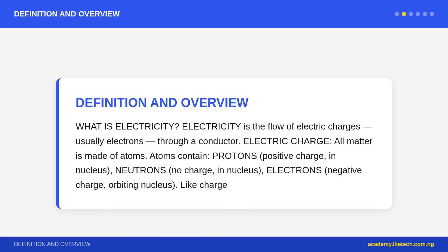Voltage, or potential difference, V, is the push that drives the current, energy per unit charge. Unit, volt, V. Measured by a voltmeter. In Nigeria, mains voltage equals 220 to 240 V, AC. Resistance is the opposition to the flow of current. Unit, ohm. Ohm's law, V equals IR.